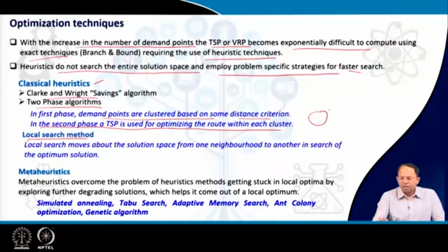One is we cluster groups of solid waste collection bins. Within each group, we determine the optimal paths, like we did earlier with 50 bins, where a route going to 50 bins has to be formed. And then the sequence in which we visit the clusters is also determined optimally. So that's the second phase of the optimization. In the first phase, we find the optimal route within the cluster. In the second, we determine the optimal route between the clusters. So it's a two-level TSP, you can say.